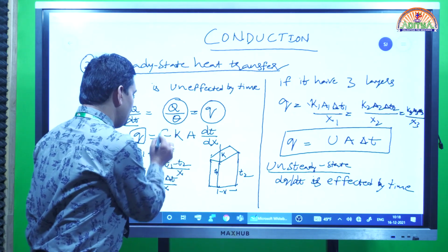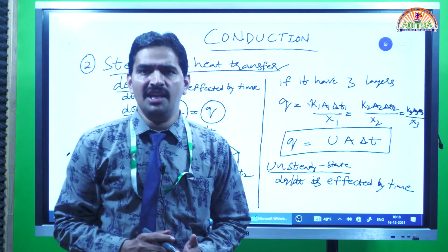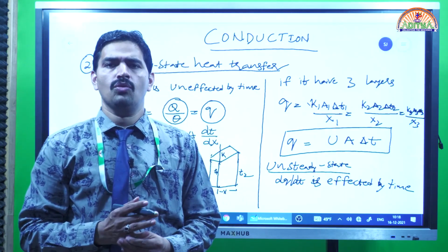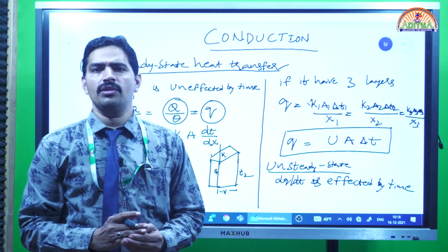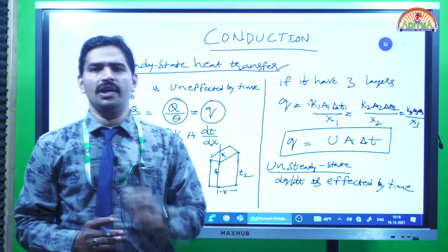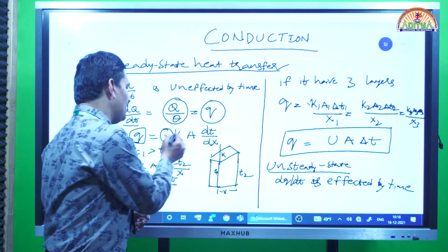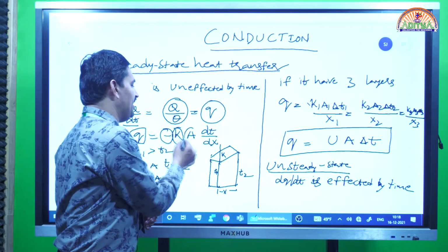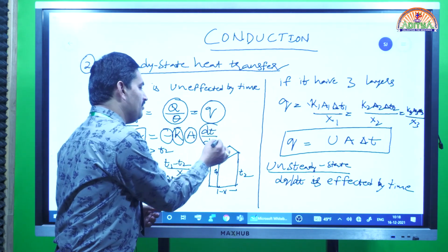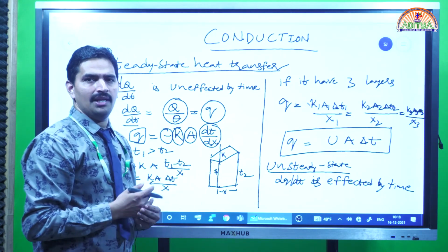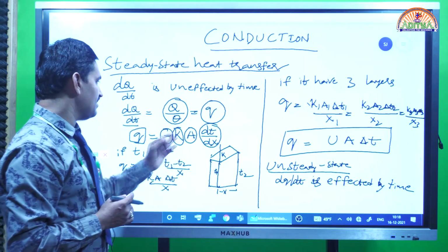Usually, what do you mean by the negative sign? The negative sign means transmission of heat from the hot condition to the cold condition. That means loss of heat is going to happen from hot to cold. That's why we depict it by means of a negative sign. As well as we know that K means thermal conductivity, A means the surface area through which heat transfer is going to occur, where dT by dx is nothing but temperature difference with respect to the unit flow path. In such a way we can discuss this equation.